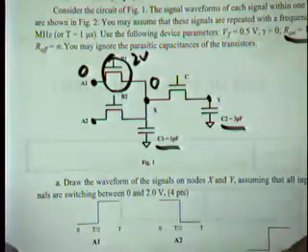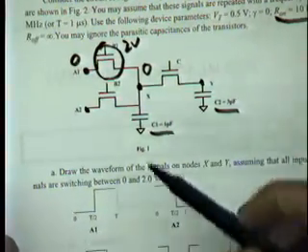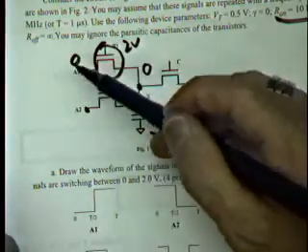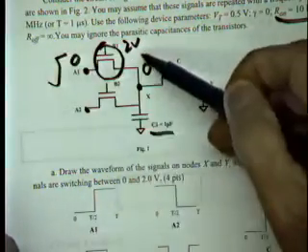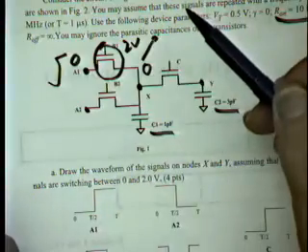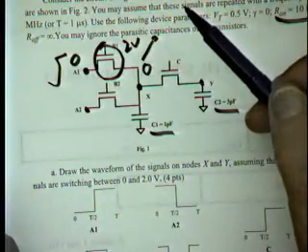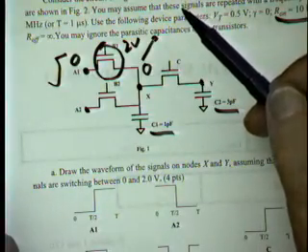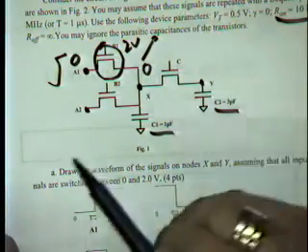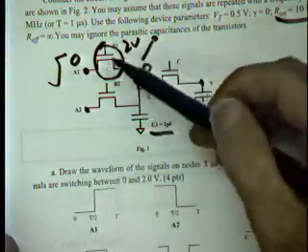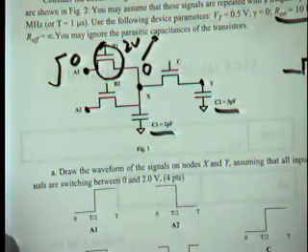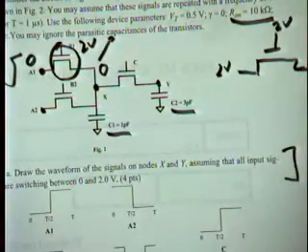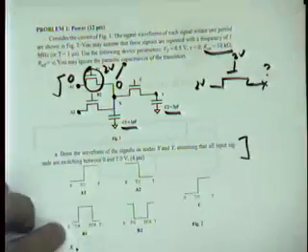So this stays at 0, or it's only when we start moving node A1 at time T/2 that this node is going to start to go up as well. The key challenge is how high does it go, right? And that's something we discussed last lecture, as I said, and was in the homework. When you use an NMOS transistor and I apply 2 volts here and I apply 2 volts here, the maximum voltage that I'm going to get here is what?